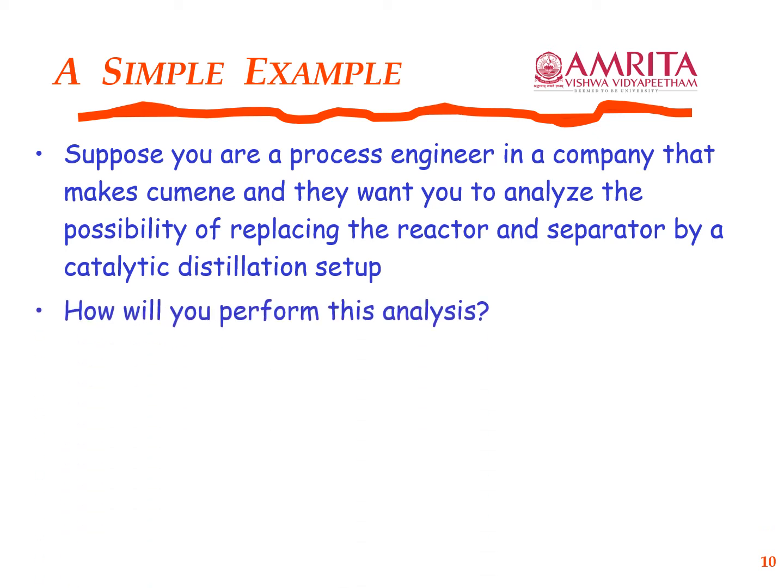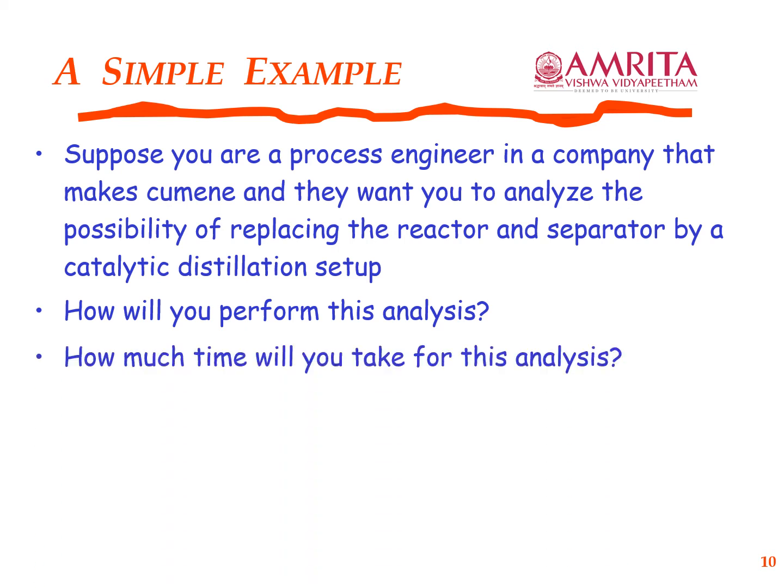How will you perform this analysis? How much time will you take for this analysis? I assume that, once you come up with some strategy, you will have to test it out if it works or not, and therefore you will have to design and fabricate, at least at lab scale and maybe then at pilot scale, a catalytic distillation setup, and then you will probably have to run all of these experiments with various feed conditions. You give benzene and propylene, those are the feed compounds, and you feed them at certain temperature, pressure, flow rate, compositions, and then run this and get all the results at various operating conditions.